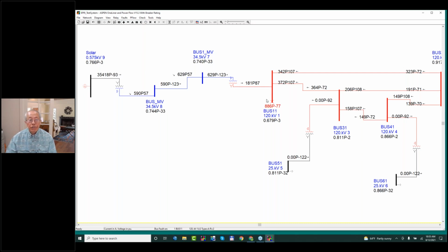And the third thing is that on top of all that, the current that it does put out acts almost like a STATCOM, because all the current that comes out is always 90 degrees, in the VAR direction, giving you VARs to support your voltage. So these are the 3 reasons why with these gadgets in the system, you actually have an easier time with the fault current flow. Okay, I think that's it.